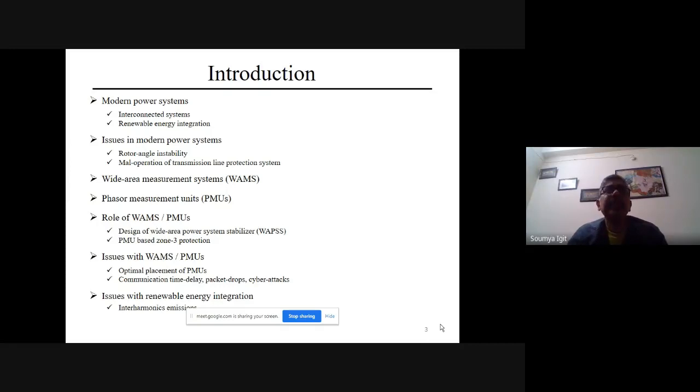You have to get the exchange of information between the adjacent PMUs, the losses to be minimal, and the different channel capacity, the transmission rate, all factors taken into consideration. You have to formulate the desirable objective function, taking the cost factor into account, and deploy the PMU at the strategic location in order to have the observability of the grid.